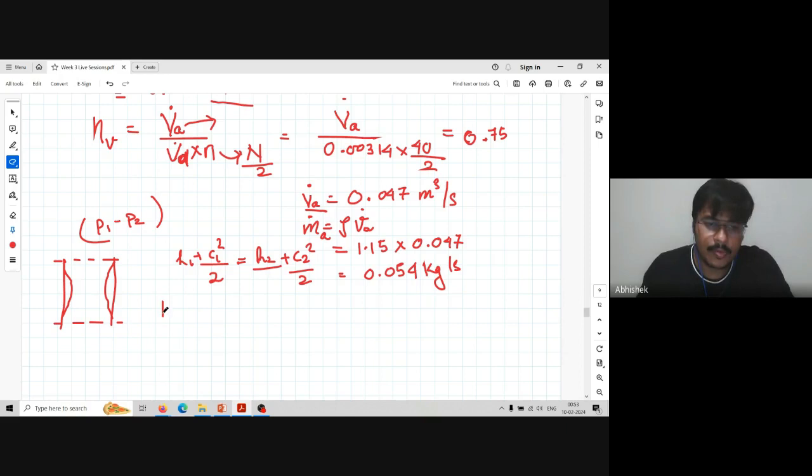So just calculate P1 by rho F plus C1 square by 2 is equal to P2 by rho F plus C2 square by 2.